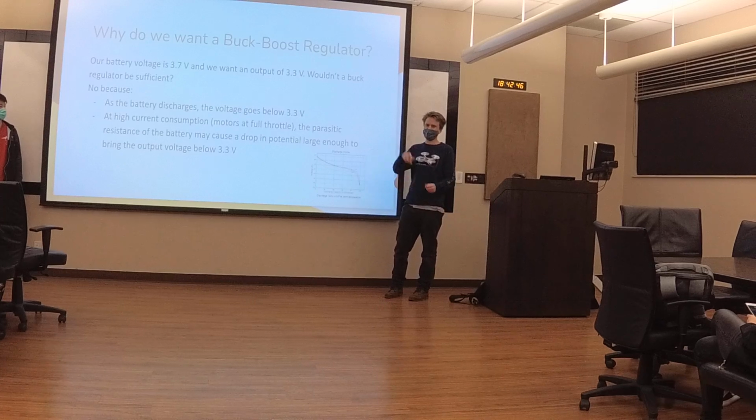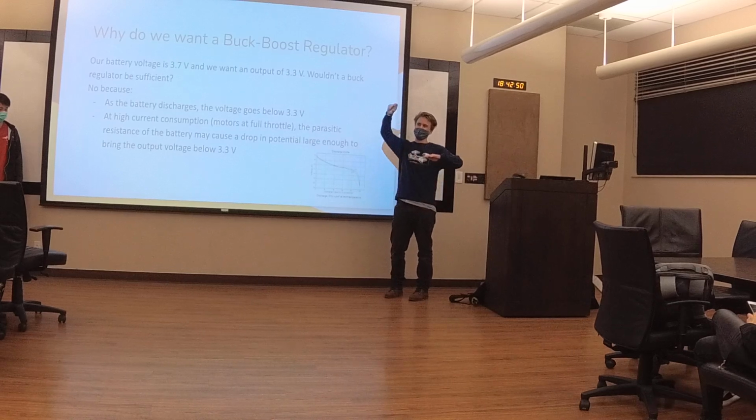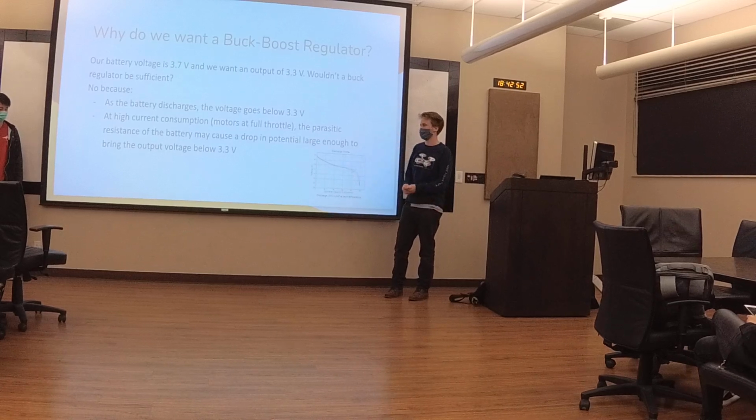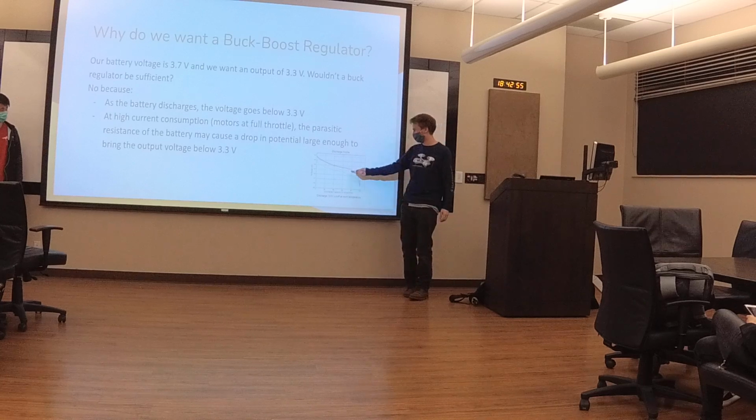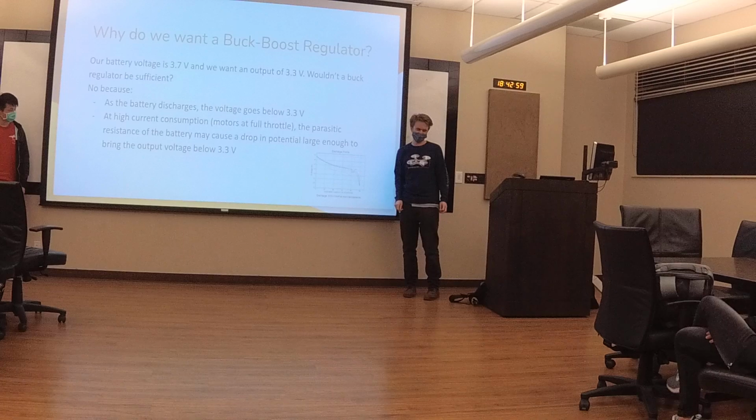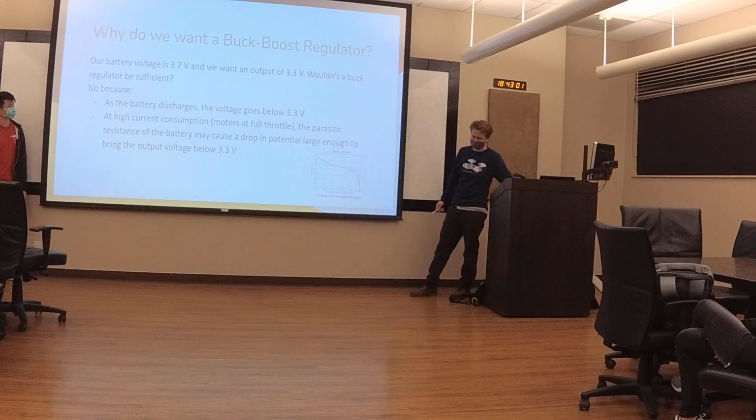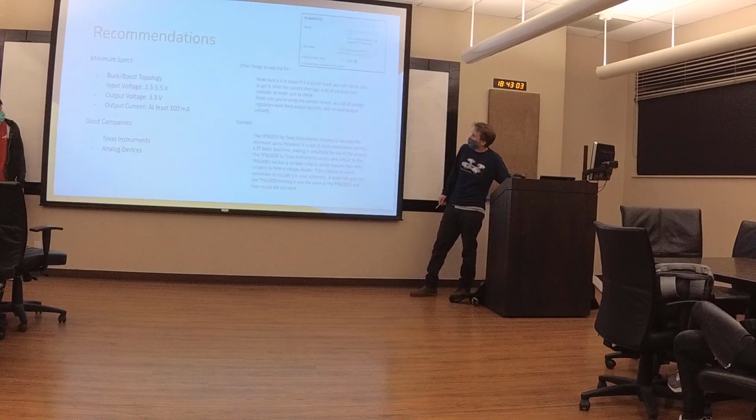That's where the boost comes in. The boost takes over the moment the input voltage drops below 3.3 volts and raises it up to 3.3 volts again. That's the reason we need it. And over here, I just include this graph again. Towards the end as well, you need a boost regulator in order for the microcontroller to work correctly.